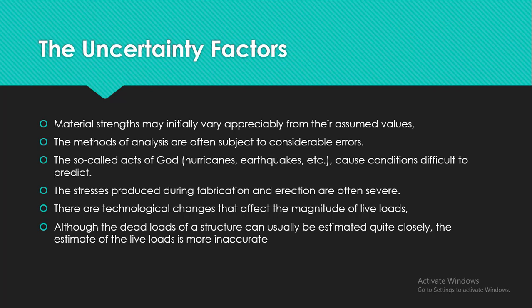Number four, the stresses produced during fabrication and erection are often severe. Laborers in shop and field seem to treat steel shapes with reckless abandon. They drop them, they ram them, they force the members into position to line up the bolt holes. In fact, the stresses during fabrication and erection may exceed those that occur after the structure is completed.